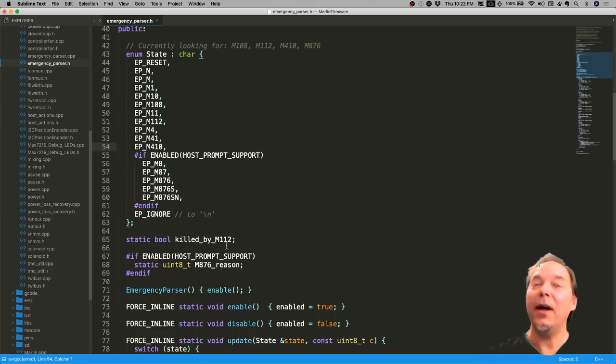Okay, mixing. Yeah, we have a mixing extruder option, which originally I implemented without knowing anything about mixing extruders except that they were there. And you move 3 motors in proportion or whatever to get the mix. So I implemented it really basically, and over time it's gotten more and more fixes and improvements. Then G-Tech sent an A10M, so I was finally able to get some testing, and they had their own extra stuff for mixing, like actual gradients and some menu items.